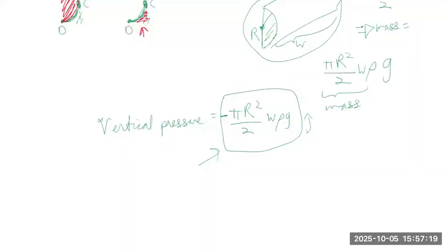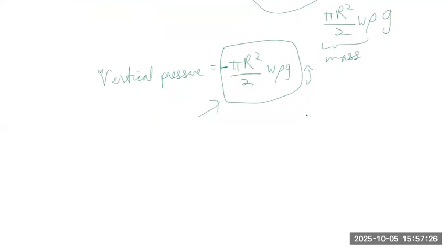So you've now seen two different ways of thinking through this problem. I'm going to offer you another way of thinking about this problem, part B. So we can also consider control volumes as we did for part A. And over here, since the vertical portion does not have any vertical forces, since the vertical pressure force will be acting parallel to that surface, we'll only consider the control volume starting from here. So only the semicircular portion.